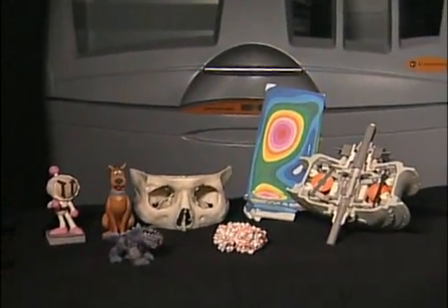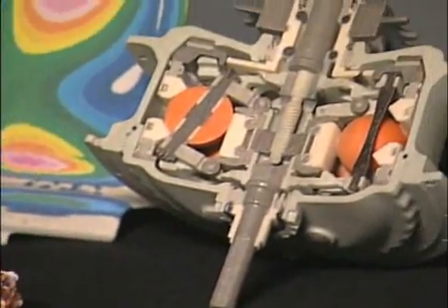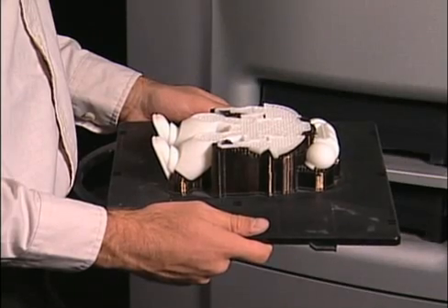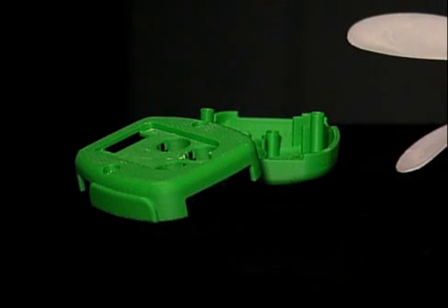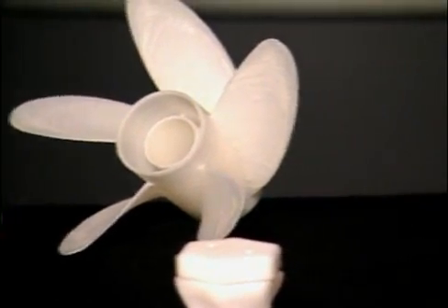Next, color. The Z Printer 450 prints in full color. Multiple colors are printed on any part. Dimension says they print in color, but it can only print monochrome, or one color at a time. The only way to make a multicolor part with Dimension printers is to assemble the different color parts into a model. Monochrome parts have some use in a school setting.